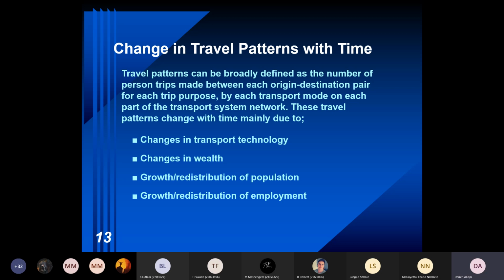Prevailing traffic conditions. Rings a bell? How your traffic varies from hour to hour on the road, the peak traffic in the morning. Many years ago, your peak traffic was perhaps half an hour, from maybe 7:15 to 7:45. Today, your peak traffic has expanded to maybe 2 hours, from maybe 6:15 in the morning to 8:15. And the same applies to your PM peak, your afternoon peak.